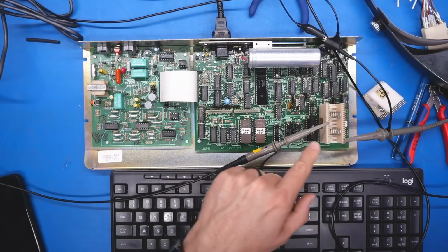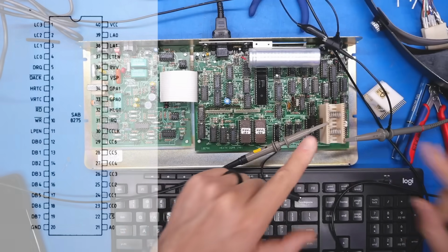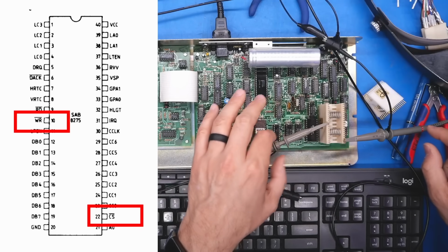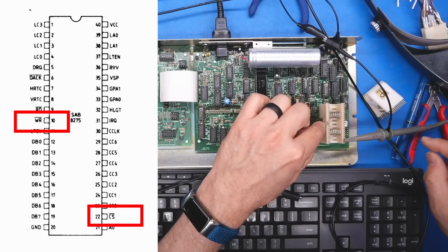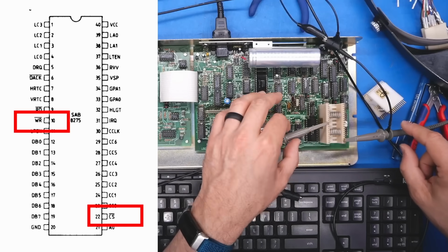So you'll notice that I have a clip on top of the video chip, and I have two probes connected to my oscilloscope. One is the chip select line, which is this probe on the right, and one is the /RW signal, which should be asserted low any time the chip is written to. So chip select is active low, and so is the write signal.